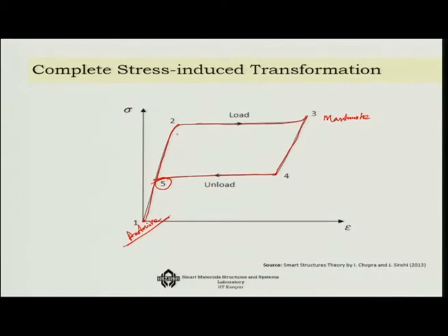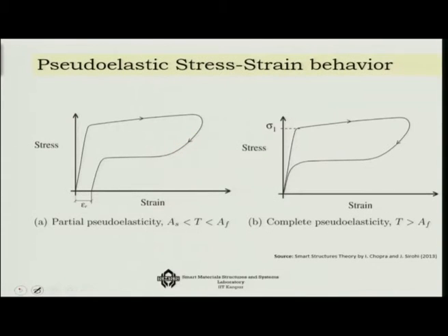So interesting thing is that this loading and unloading at a high temperature has this much area covered by it, and this area is responsible for the hysteresis, or for that matter for structural damping. It is heavily being used today for structural damping. So this is the pseudoelastic effect.